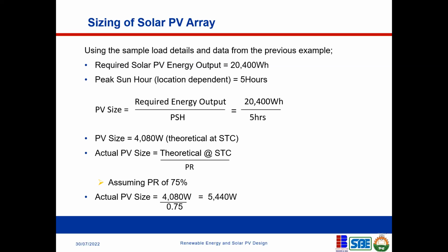No, we need to know exactly for a particular location. If I'm in Maiduguri, you need to read off exactly what the PR is. But the PR depends upon the temperature of the module. That's what I'm saying. There are graphs which have been done, which you can read from. You can read out the PR for various temperatures. If you use the software to select your location, I think the software will equally suggest some of the performance values.